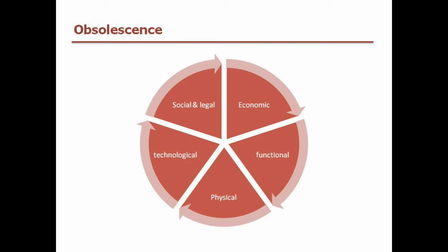But having said that, it actually gets very difficult, not just because of the data that you need to forecast and look for, how long a material or a building component will last. But in practice, we have to consider several things, such as economic life, which is the period over which the occupation of the building is considered to be the least costly alternative for achieving a particular objective. Also the functional life, where that building or the component of the building ceases to function for the same purpose for which it was really built.